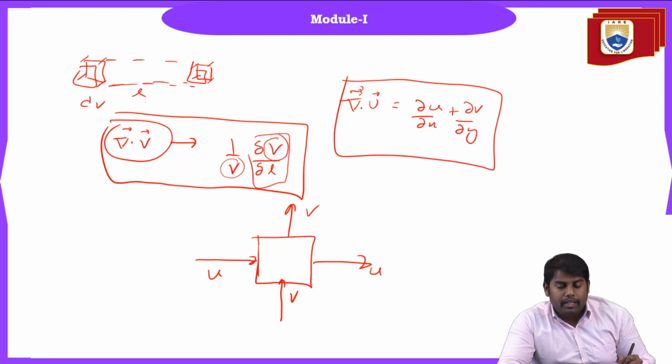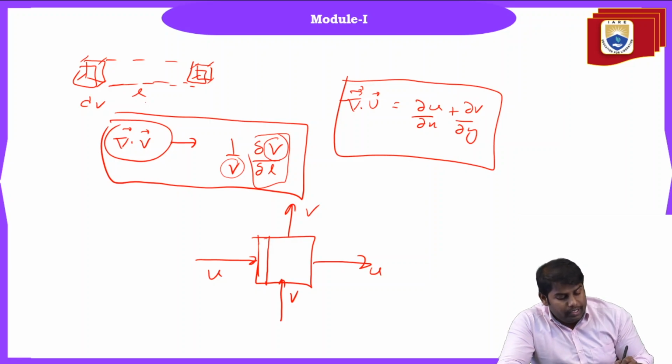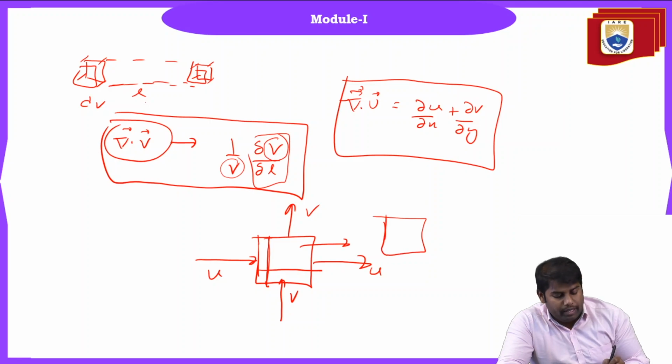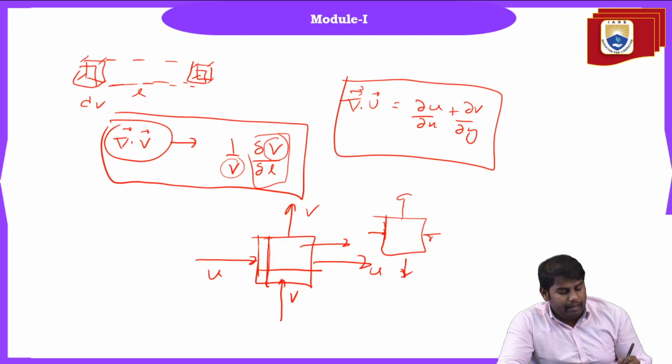Now, what is the meaning here actually? So, dou u by dou x and dou v by dou y. When there is a change in velocity, what is the amount of distortion that is happening, let's say because of this inflow? If this control volume is moving with the flow, there is distortion happening along the y direction and distortion happening along the x direction. Because of this flow, the new control volume shape has decreased in this way. So it has translated. The compression may happen or the elongation may happen when it is traveling from one region to another region.